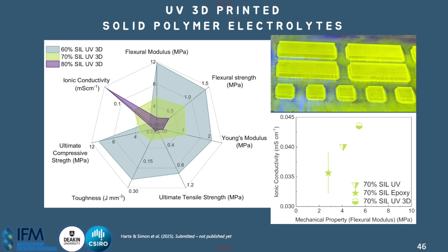and the benefit of moving away from that epoxy resin cured system where we had issues with the catalytic curing, we couldn't degas the resin, and we moved to a system where we could mix homogeneously, degas efficiently, and cure initially in the mold cured system as a bulk efficiently, and then actually make a stronger material when we cured line by line in the 3D printing technique.